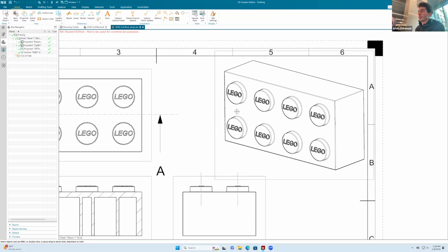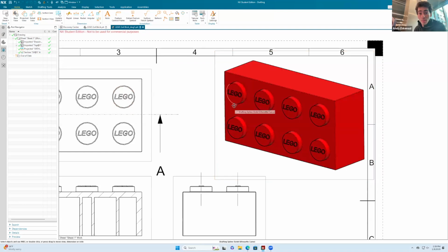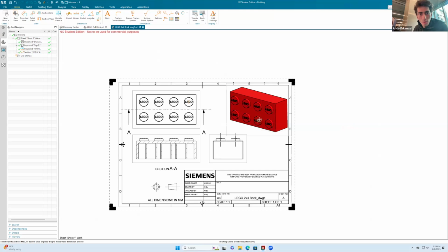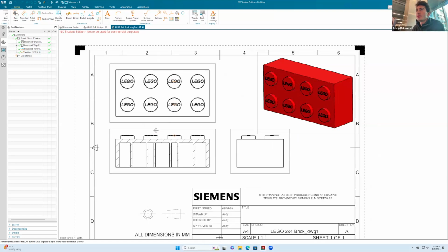Yeah, I like it over there, right? But if you right click here, let's go to different text, look to shading. You can say fully shaded. Let's say okay. Very good. That way, this is normally the only view out of the drawing views that is colored. The rest are normally shown in the wireframe, at least in this particular setting. Let me leave this in here for now.